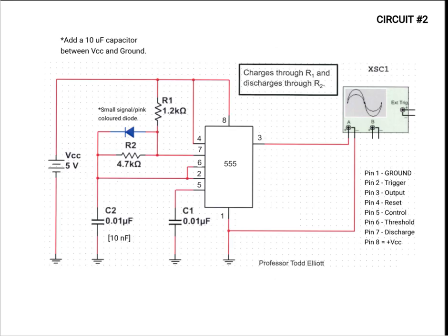Add a small signal diode. It's important that it's a small signal, not a power diode, something like a 1N914, because it turns on and off much quicker.